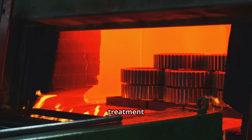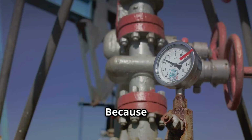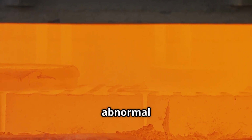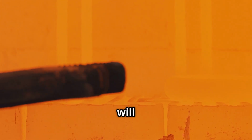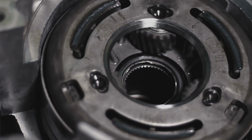Obviously, the metallurgy and heat treatment of the metal are very important to this lubrication regime. Because an oil's viscosity is directly affected by temperature, it is also clear that incorrect or abnormal operating temperatures will interfere with the formation of the elastohydrodynamic lubricating, or EHL, film.